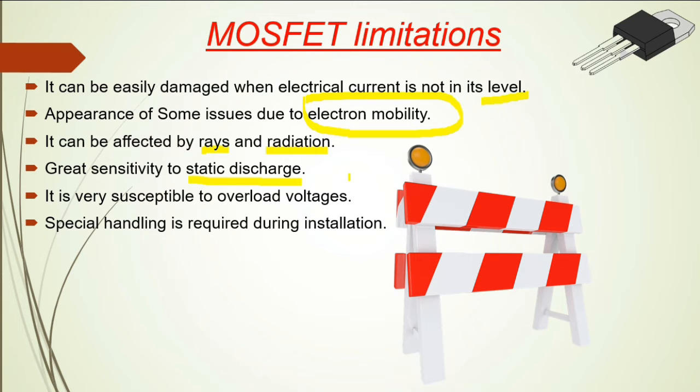We should always pay attention to static discharge because the MOSFETs, and not just the MOSFETs, but all electronic components, capacitors, resistances, diodes, all electronic components can be damaged by static discharge. So you should pay attention when you handle MOSFETs. It is very susceptible to overload voltages.